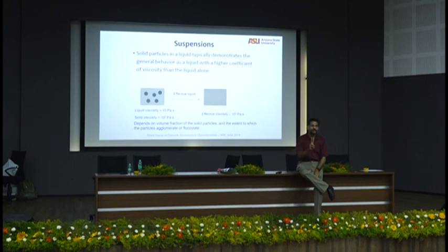So you have two length scales or two sets of length scales acting in the same material. So you have a rheology at the cement paste level, where the paste is sliding in this water medium, and then the whole paste and water acting homogeneously as a gel in which aggregates are trying to slide. So you have two optimizations you have to do when you do concrete rheology. And right now we really don't have to worry too much about it because we have really nice admixtures that will take care of doing all this by different chemical mechanisms, so that you don't have to spend too much time on seeing how this happens.